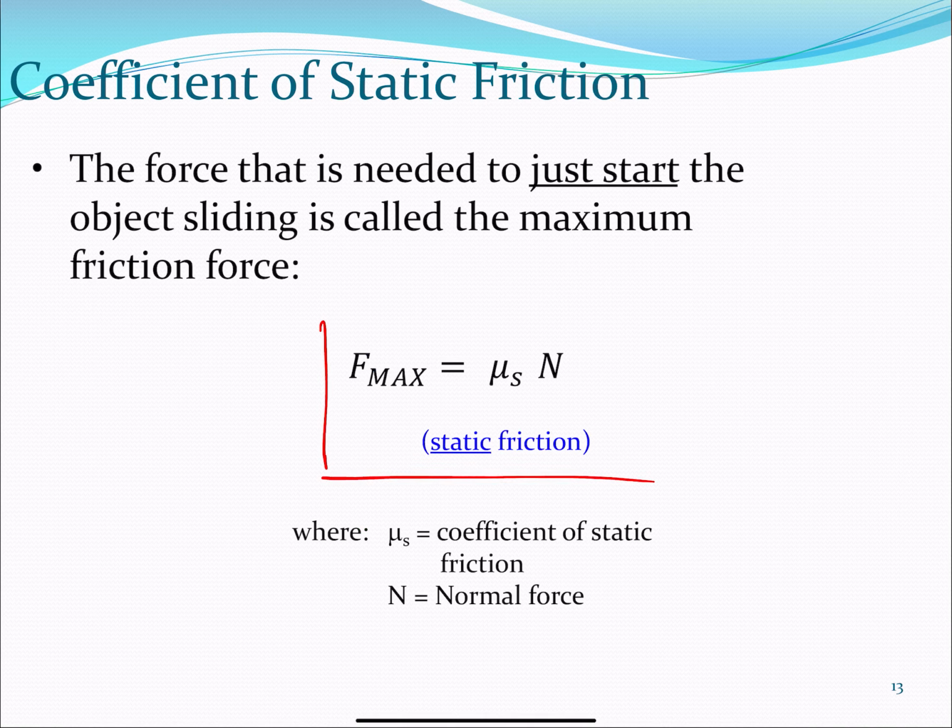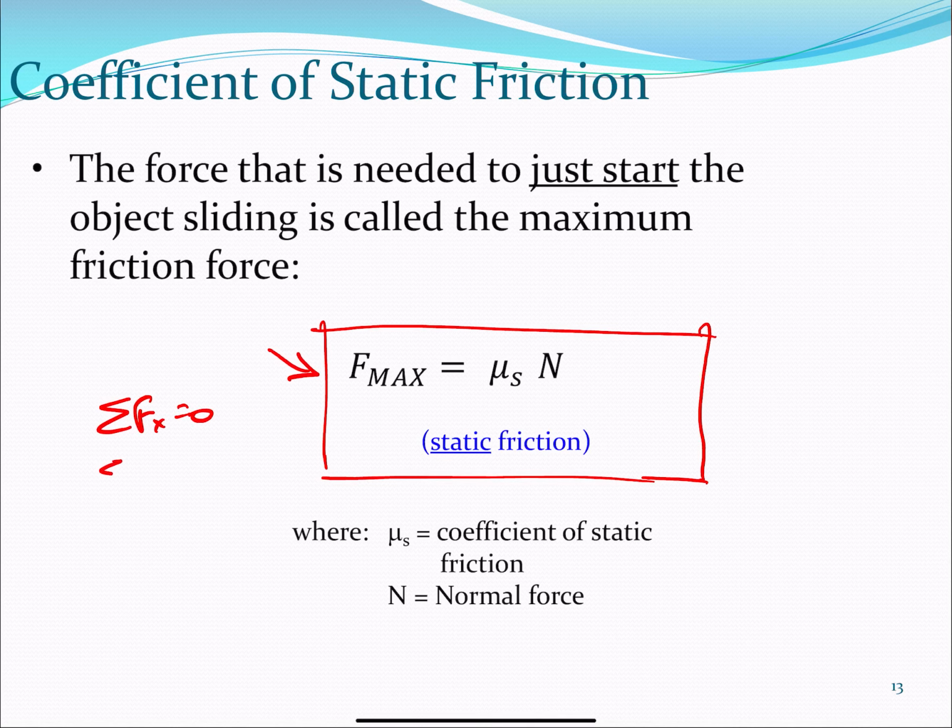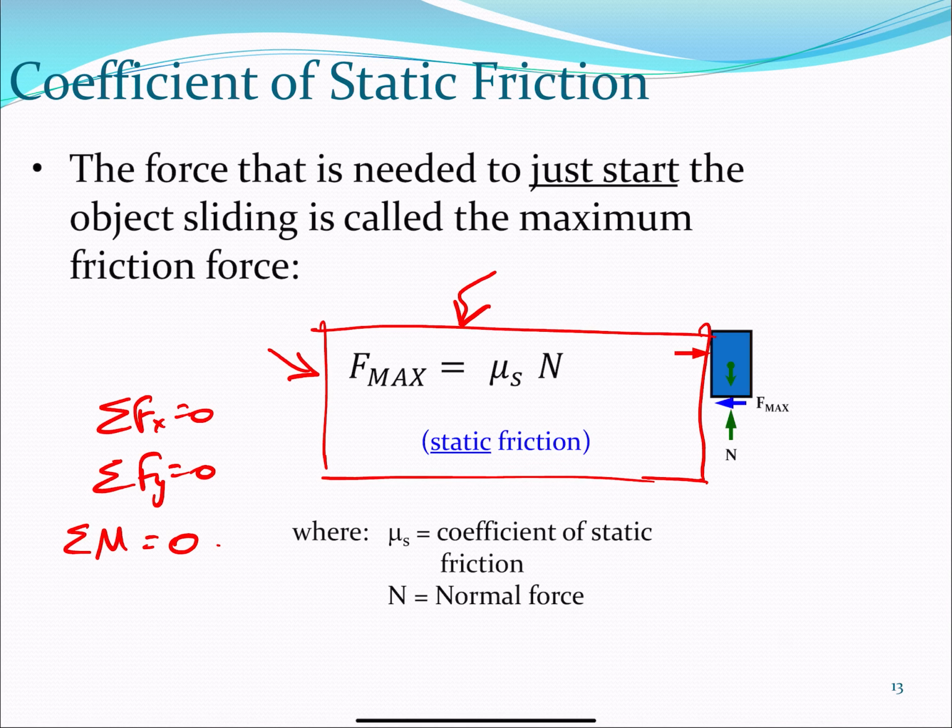That is the first formula we are going to investigate. By the way, all we need is this extra formula. The rest of the equations we need to examine friction problems we already have: sum of forces in x equal to 0, sum of forces in y equal to 0, and sum of moments equal to 0. So we have all the tools we need. We just needed this equation here, so that will allow us to tackle friction problems.